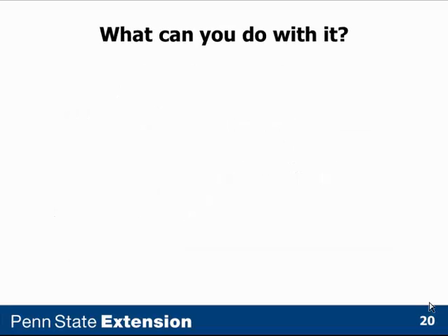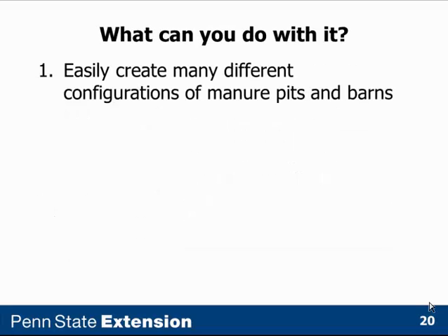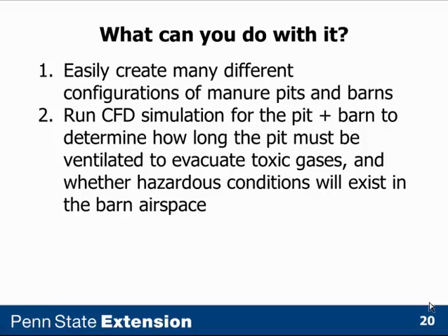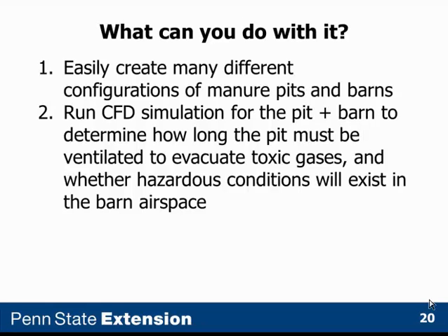Now what can you do with it? You can easily create a range of different configurations of manure pits and barns. You can run CFD simulations for the manure pit if it's a standalone case, or for the manure pit and the barn above it, to determine how long the pit must be ventilated to evacuate toxic gases. And also you can use the simulation to determine whether by ventilating the manure pit you develop a secondary hazardous condition inside the barn airspace. That's important to know too.